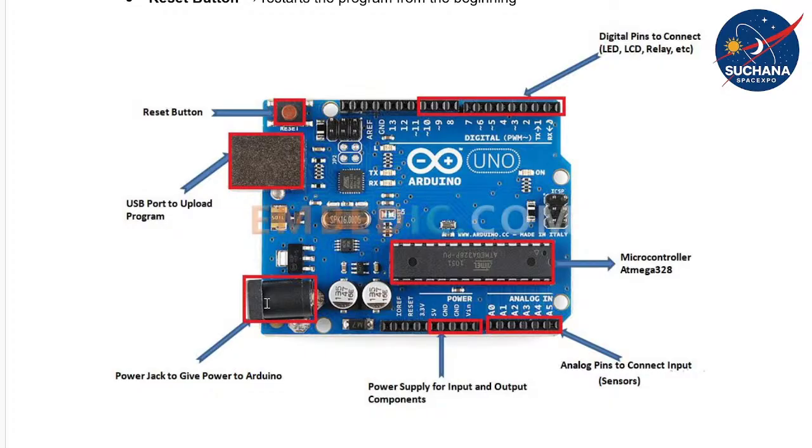Once you configure the pin in output mode, every pin will have two different states: a high state and a low state. First you need to set the specific pin as either input or output. For an LED, it's output, because you need to supply the voltage through that pin, and only then will the circuit get closed. One terminal gets a positive supply, and the other terminal is connected to the ground. The circuit of the LED gets closed and it will power up. From this we can understand it must be configured in the output state.